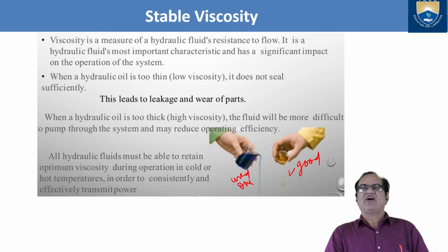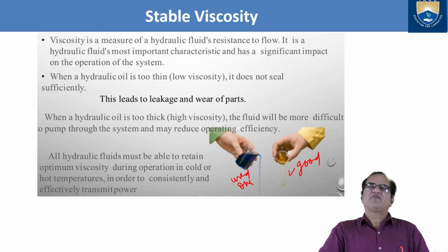Viscosity is a measure of hydraulic fluid resistance to flow. It is a hydraulic fluid's most important characteristic and has a significant impact on the operation of the system. So this viscosity is very important. If the viscosity is lost, the system performance will be tremendously reduced and component failures will start. When a hydraulic oil is too thin, low viscosity, it does not seal sufficiently.